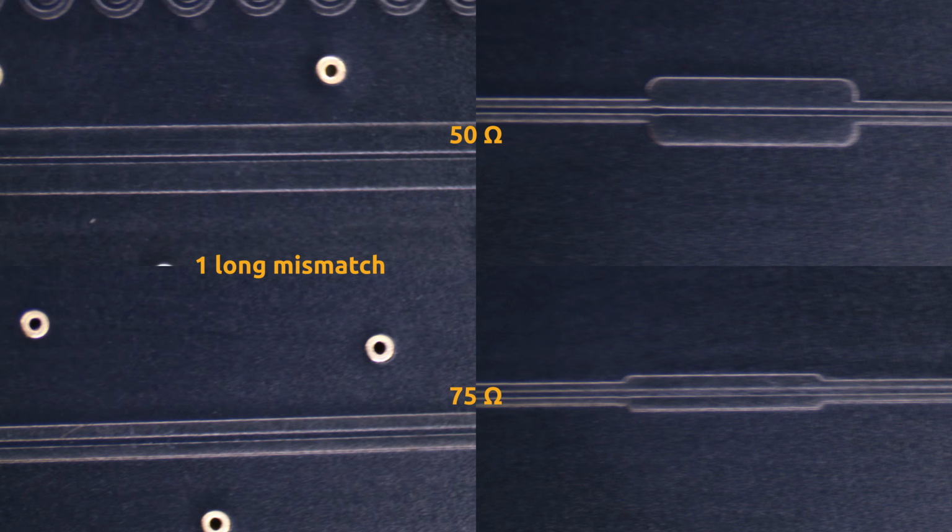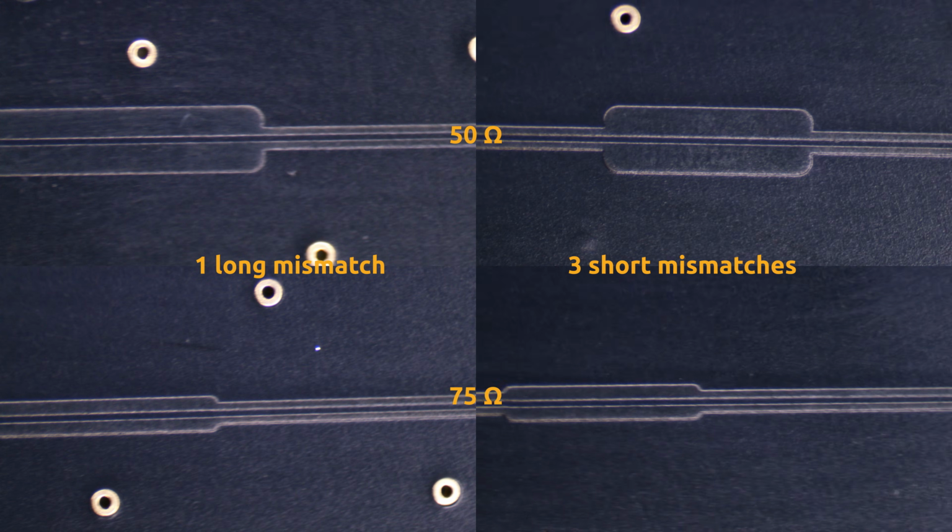I have some traces on this demo board with different mismatches. We're going to take a look at 5 differential 100 ohm pairs on this board. One of them is just a really long trace without any mismatches. 2 of them have major mismatches of about 50 ohms, and 2 of them have minor mismatches of about 75 ohms. Each has one with a long mismatch and one with 3 shorter mismatches. We're going to take a look at the signal integrity of all of them.